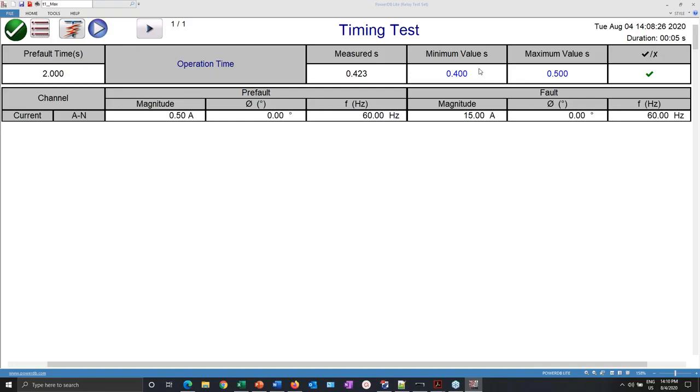Of course, the tools that we have allow you to do this kind of testing more easily, but what our tools do essentially is use this same concept. They inject magnitudes into the relay and sense the outputs of the relay and then evaluate the tripping or not tripping of the relay, depending on the conditions and the settings that the relay had.